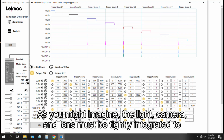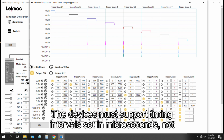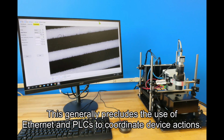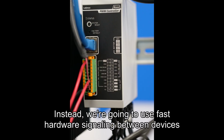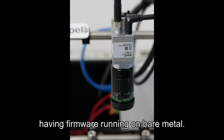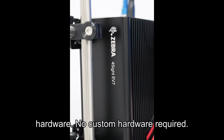As you might imagine, the light, camera, and lens must be tightly integrated to perform a rapid imaging sequence. The devices must support timing intervals set in microseconds, not milliseconds, if the task is going to be completed quickly. This generally precludes the use of Ethernet and PLCs to coordinate device actions. Instead, we're going to use fast hardware signaling between devices having firmware running on bare metal. And we're going to do this using commercially available off-the-shelf hardware, no custom hardware required.